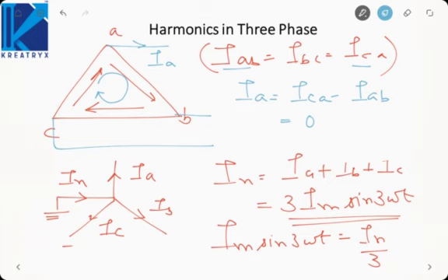So this is about the harmonics in case of three phase. So what have we observed? 3n plus 1 and 3n minus 1 harmonics can always be present. But for triple n harmonics to exist, we need either a closed loop or a path to the ground. But there is no such necessary condition for the fifth and the seventh harmonic, that is 3n minus 1 and 3n plus 1 harmonics respectively. Now let us see what are the various types of constructions in case of three-phase transformer.